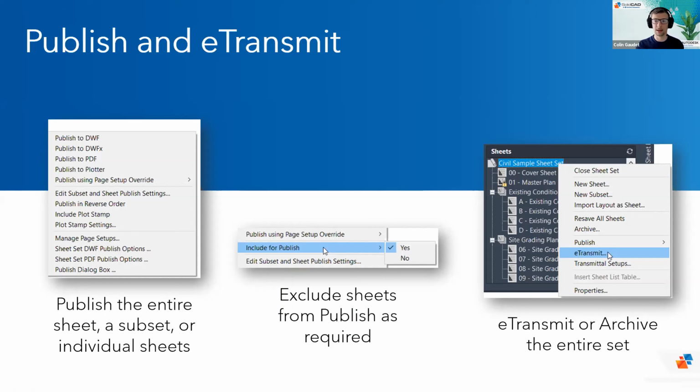It's because they only sent you the DWG as opposed to e-transmitting that file. When we e-transmit the file, it collects every connected file into that DWG and bundles it all into a zip folder, and then you share the zip folder. That's a really basic look at ETransmit.